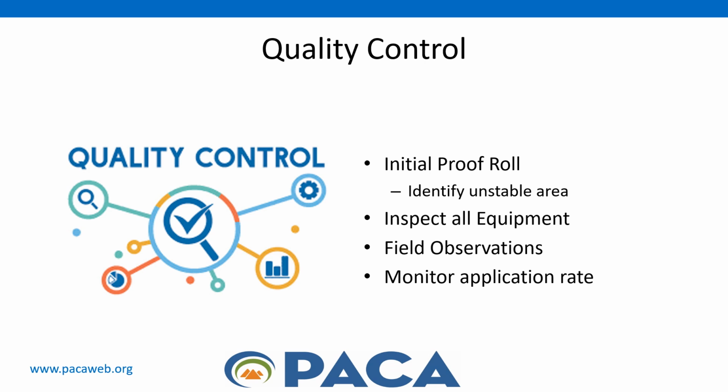A test strip may be constructed to monitor the cement application rates and depths of treatment. This should be done after the contractor's methods have been established and the field observations performed. The application rate should be monitored to ensure accuracy. The mixing should begin within 30 minutes of the cement placement. The effective index of mixing should be verified during this operation to ensure that the proper gradation and pulverization depth is achieved.